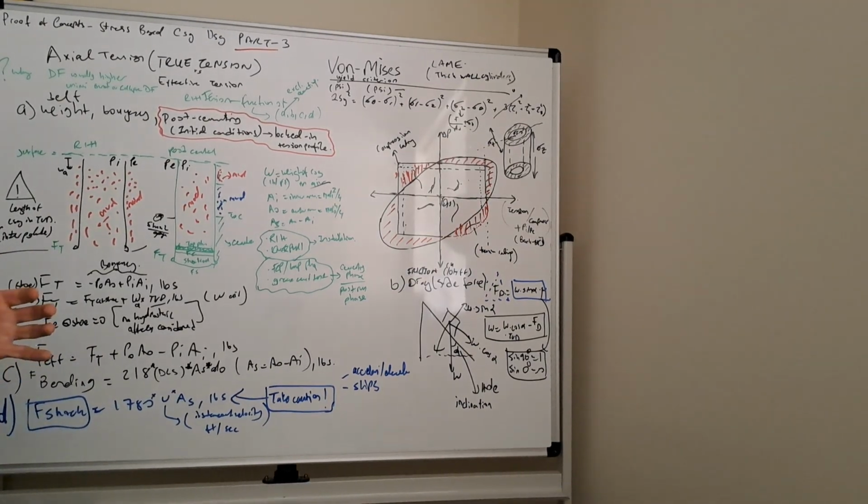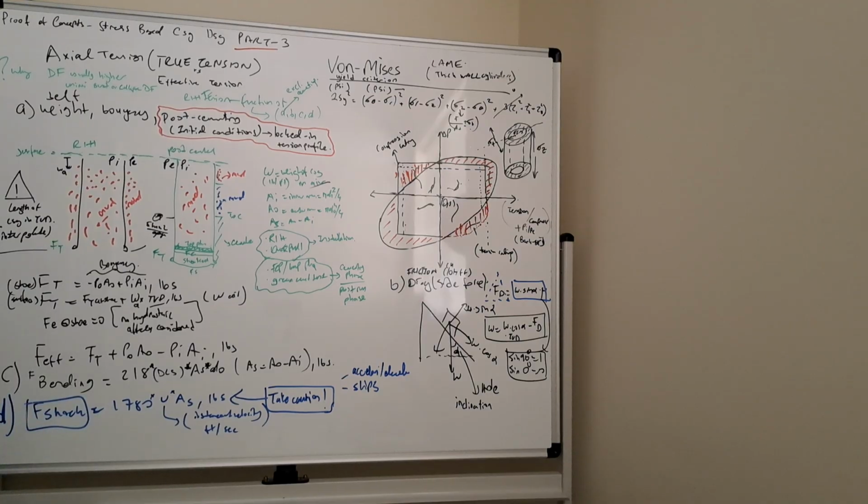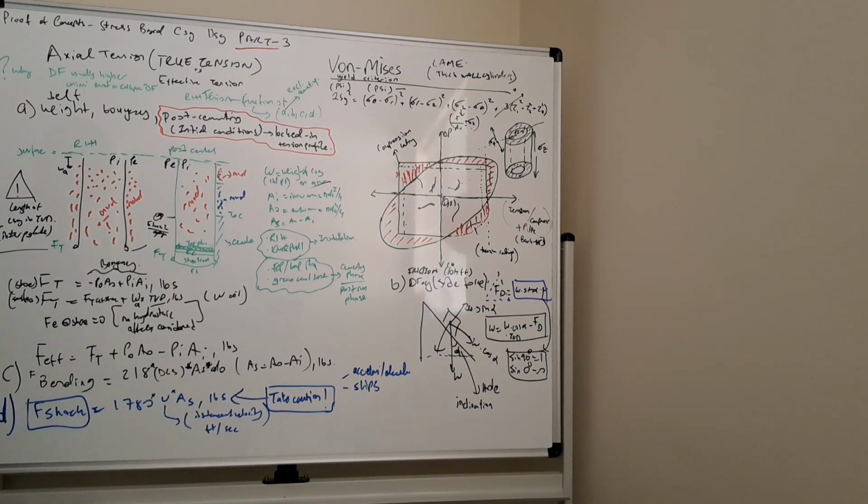So effective tension in reality is not a real force. It's more a criterion to decide on the buckling, whether the pipe is buckling sinusoidally or helically or not, and what we can do about it. I'm going to talk about that a little bit on the second page.